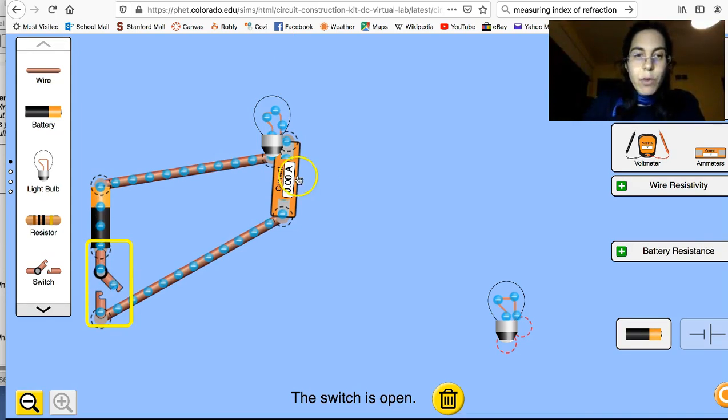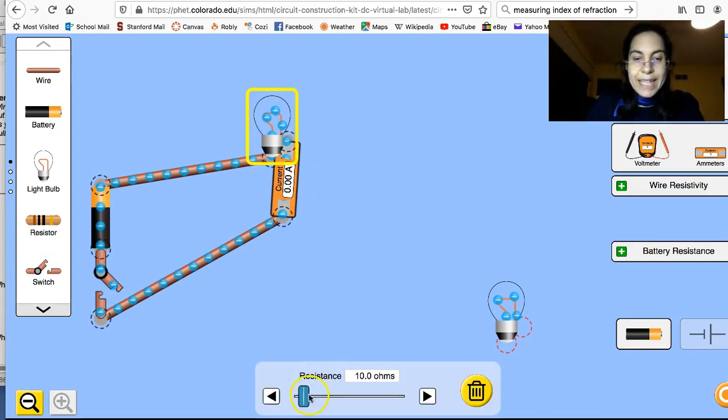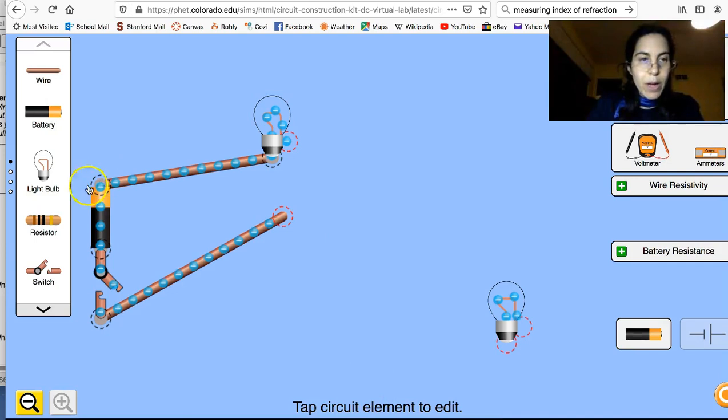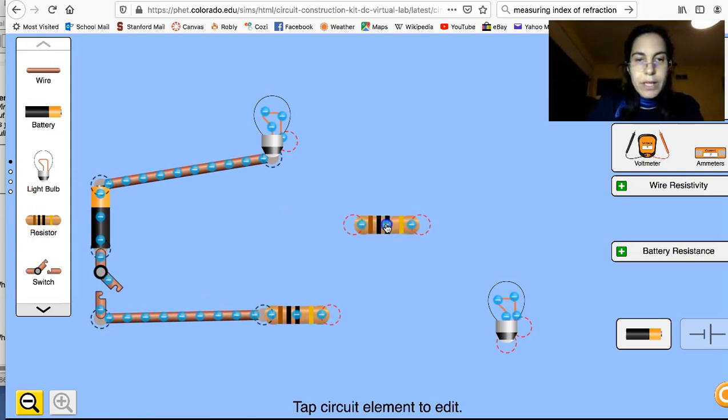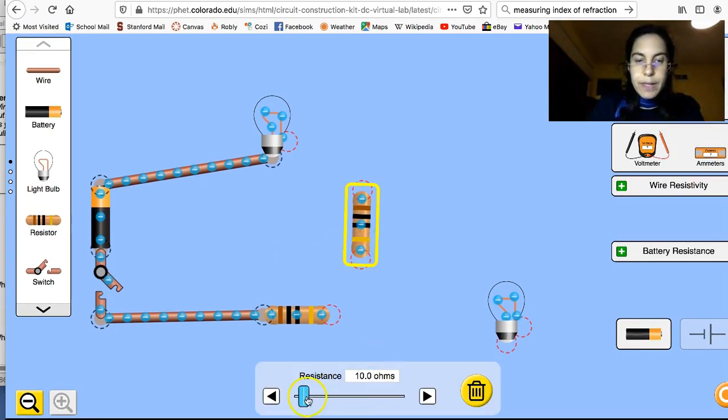That is because every one of these bulbs has a certain resistance. The more resistance you have, the less current will flow. That's definitional. Resistance is how hard it is for the current to flow. In a series circuit, you are adding checkpoints. If you have more resistors, you have more traffic lights, more checkpoints, more things holding you up. Add more and more and more resistors. You're going to get higher resistance, and the current is going to go down.